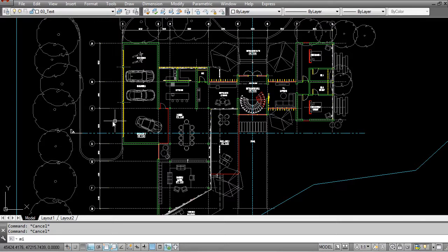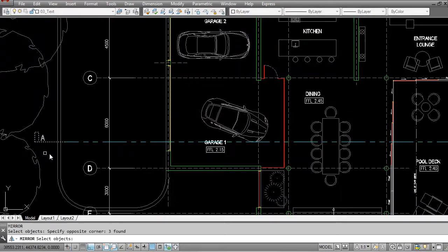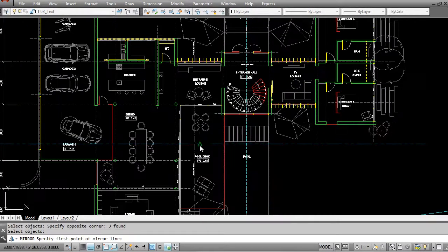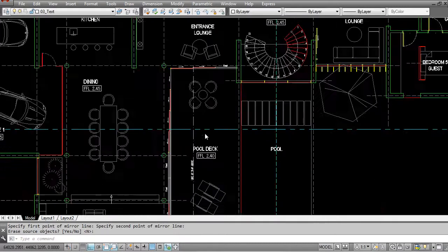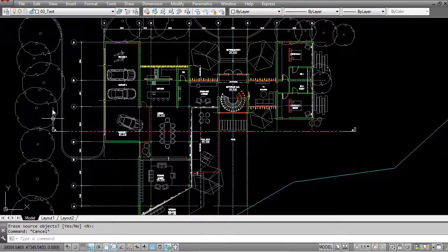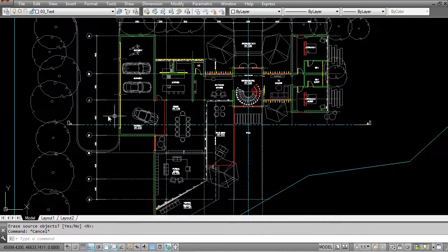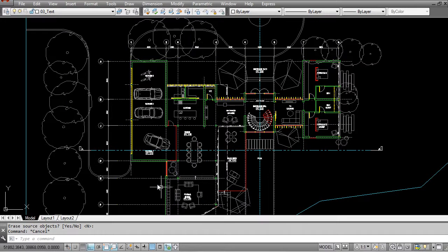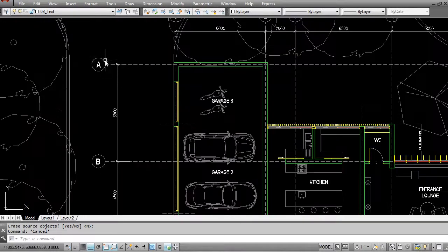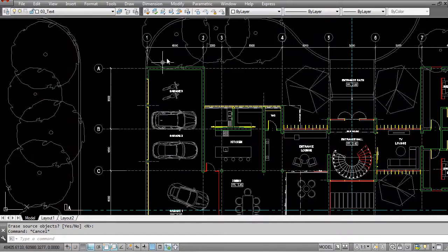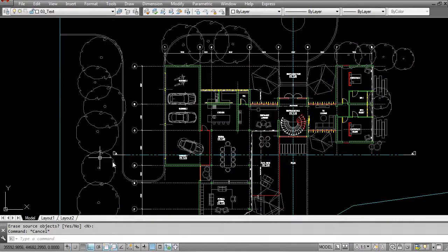And we're going to mirror the A symbol to the other side. So now we have a section AA. Now the next section that we do, if we had to do another one, would be called BB. And remember that if it is cutting in this direction, it will also be called BB. It doesn't have any relation to the grid line symbols A, B, C, or any of these numbers. So the two are separate systems that basically function in their own domain.